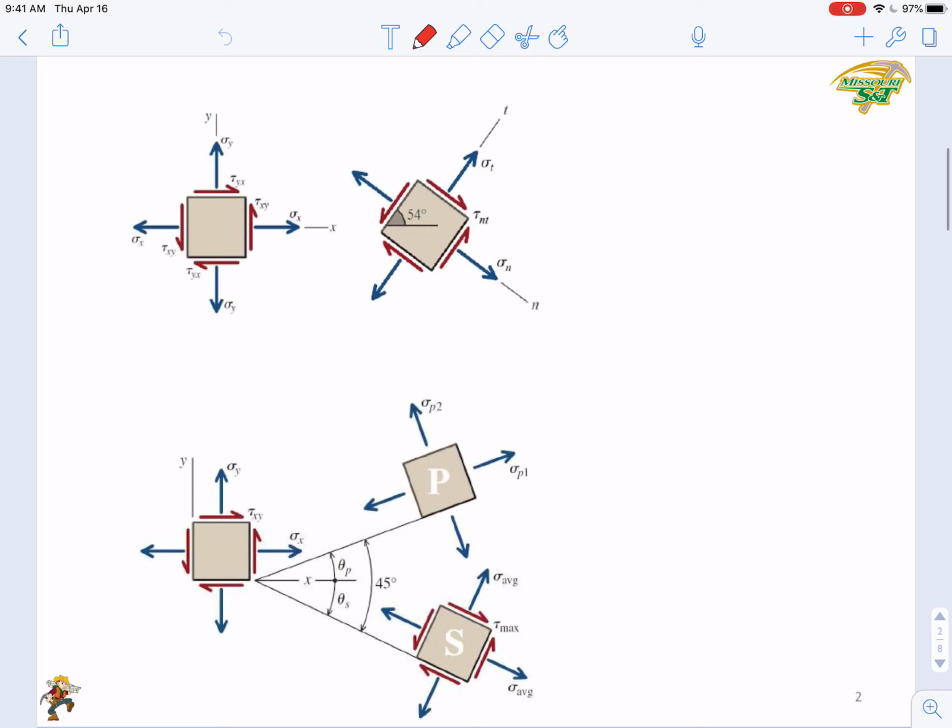So in the last lecture, we have shown several equations that we can use for stress transformation. Let's see, we start from a random stress status, which includes several components. That is sigma x, sigma y, the two normal stresses, and tau xy, tau yx. Those shear stresses will have the same magnitude, right? So this stress status can be denoted by sigma x, sigma y, and tau xy. Okay, you just have these three components at a random point.